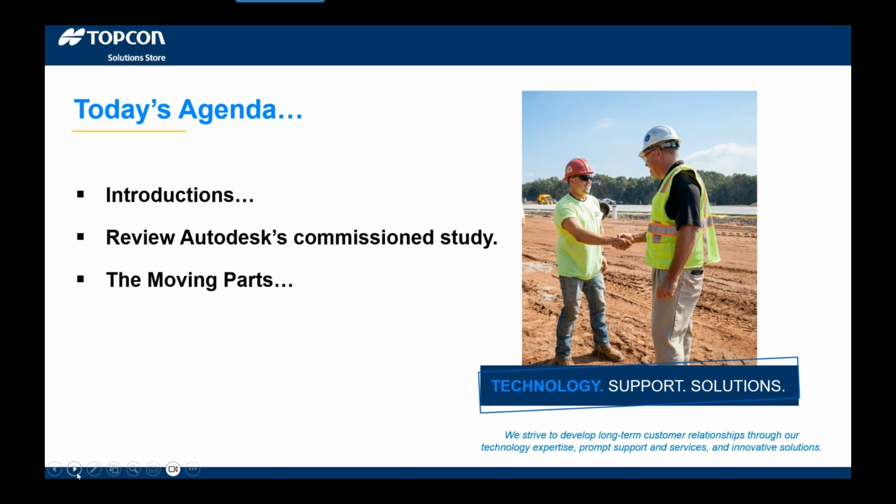Now, I'll be honest, I've run into really complex surfaces that I've tried to run the tool on. And like anything, it's doing its best to perform the calculations, but you're never sure until it comes back to us and we take a look at it. Then we have to go back through that process, possibly change some of the zone hierarchy around, or add tighter constraints or whatever it may be to arrive at something.